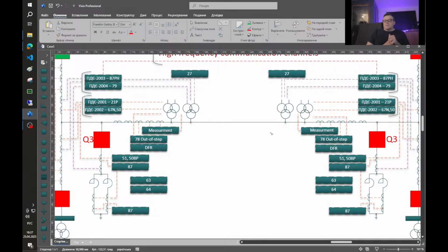This is not only because of the Ferranti effect, but also after like half of a second the line can start to generate a second harmonic, and this can be a problem because operational staff don't see this second harmonic, because all measurement devices are tuned to the first harmonic.